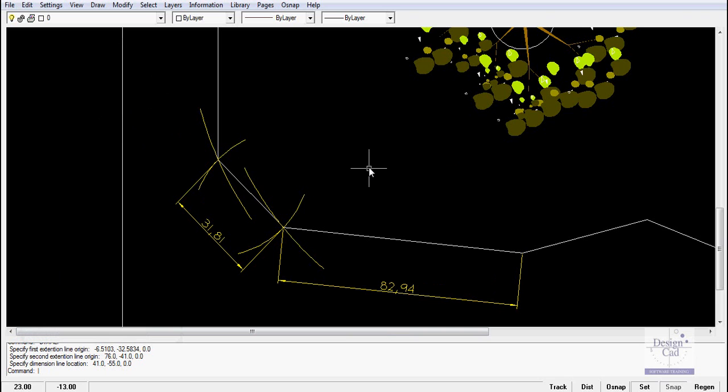So I hope that gives you some idea of some of the things you need to think about when you are laying out a site using feet and inches and using some dimensioning and using some triangulation to get things accurately located. Some people, of course, zoom in on their site using Google Earth and copy the picture, which is accurate enough, and then just trace over their aerial photograph essentially of their site. It depends on the level of accuracy that you require as to the level of detail you go to.